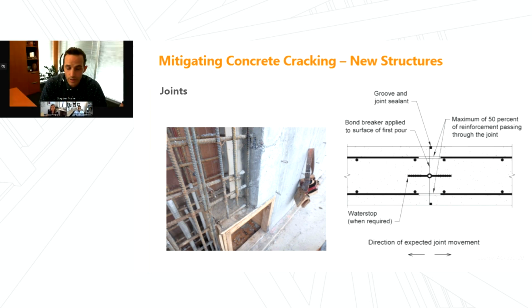So this is talking about where we mentioned, where are we on that process of corrosion? And it sounds like in this case, there's at least one area where it's manifested in surface damage, but doing a more comprehensive assessment to say, okay, well, why is it spalled in that one location and potentially not the other location? So perhaps in that area there might have just been shallower cover because the tie of the column was shallow there, and that's what's corroded.